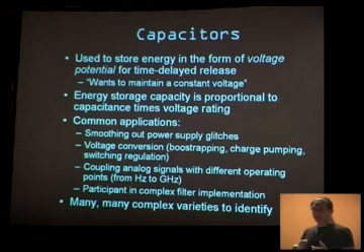A lot of people send me emails saying, oh my God, I knocked off a capacitor from my motherboard, but it still seems to be working. Why is that? It's because you probably knocked off one of these smoothing capacitors, and they're placed paranoidly around the board, very conservatively.